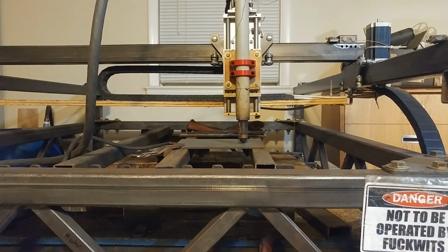Secondly, this manual setup is a surprisingly good solution. I used my plasma torch like this for probably 2 or 3 months before I managed to build the Arduino based one, and it works surprisingly well. As long as you have the ohmic sensing before every cut that we detailed in the last video, then you shouldn't need to do too much adjustment of the Z height in the middle of each cut. So if you just don't mind babysitting the machine and doing that little bit of adjustment yourself, you can get a pretty good solution just like that. Especially if you're just working in your basement shop just as a hobby the way I am.